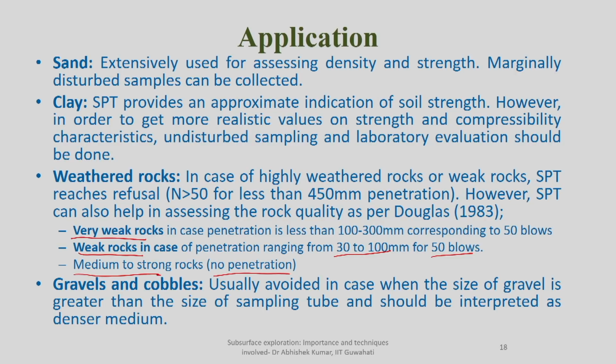Cobbles and boulders also, you can do the test, but provided the size of the gravel is not too large, otherwise your sampler will not be able to contain any sample, and that's how you will not be able to do the test on cobbles and boulders.